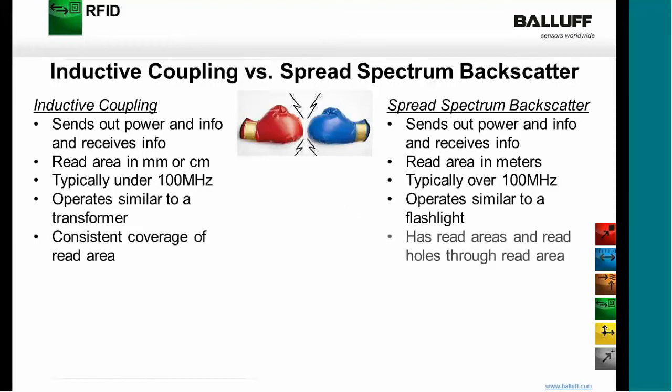Now with the inductive coupling style, the area of range in which it's able to communicate is consistent. So it doesn't matter where the tag is positioned within that coverage area, it will always read and write data to and from the tag.